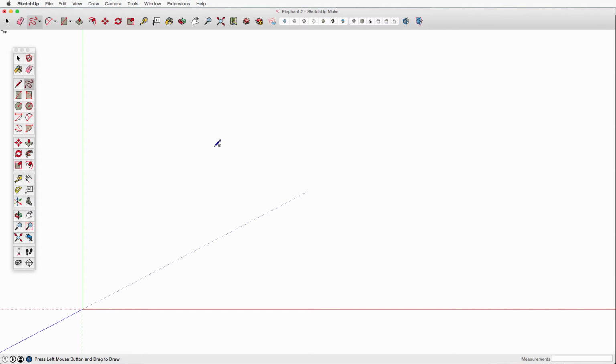And literally, you can draw like you're a first grader. So if you were drawing an elephant in first grade, you're probably going to draw a round head. And as long as you complete that circle or get close, see there, I didn't get close. It didn't fill in with the surface. Because one of the ideas in SketchUp is as long as you draw a curve and get it close, it's going to fill in, and this now has a surface. I'm going to press the spacebar and I'll show you that I can select the line around it, or I can select the surface in the middle.